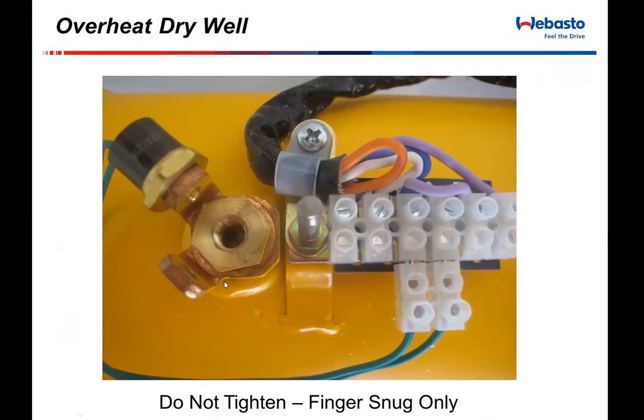That melt fuse is a part to where if I had a fleet locally to me that had 10 Webastos inside of it, I would make sure I had a good handful of those things on the shelf at the beginning of each season. It's a rather popular part that people go through, but that part is put in there obviously for a reason, and that's to help overall protect the heater in regards to being very, very hot.